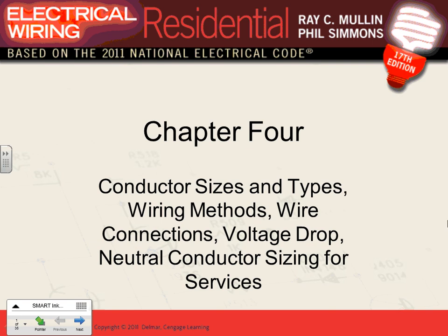Chapter 4. Very important things, as I said about Chapter 4, guys, is conductor sizes and types and the ampacity for the conductors. We're going to focus slightly on the residential today, but I would go a little bit further because you're going to be with me for the commercial industrial, and I'm going to walk you through 310.15(B)(16), how to use it to size a conductor based on voltage drop as well as based on the rating. So very, very important how to use it, and we're going to take a couple of examples.